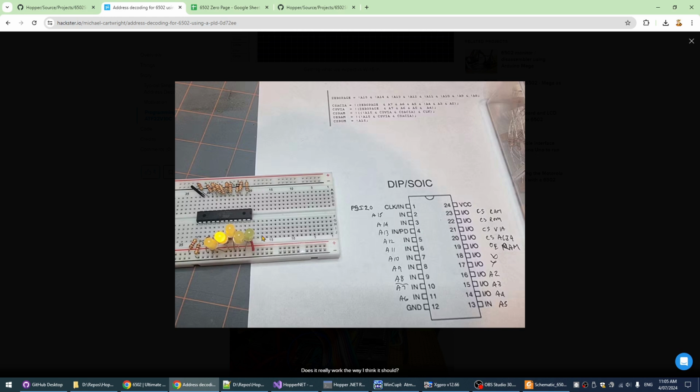They've got inline resistors as well, so they don't draw too much current on the outputs. So I could manually program an address in here to verify that my program was working as I expected it to. This is a fun exercise to do if you don't have your board up and running yet, or you get this component first in the mail and you want to play with it: just manually test that the program is what you expect it to be using a breadboard.